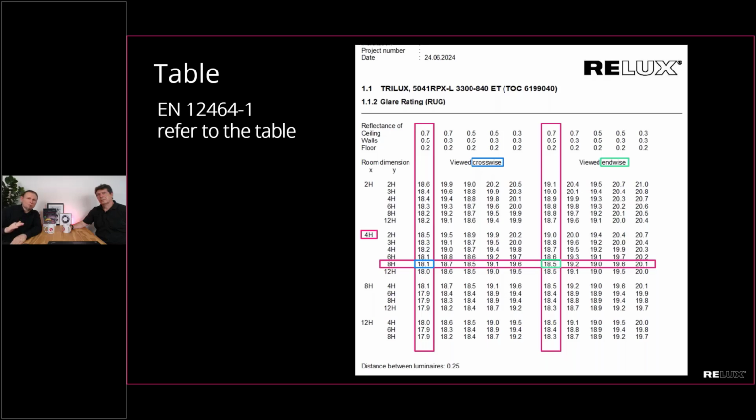But if there is no room involved in the situation, then this is some kind of standard room size which is referred to in a lot of data sheets. So if you find just 1 UGR value for a luminaire, then this potentially means 70, 50, 20 and 4H, 8H for the room orientation. I cannot tell why in particular it's 4H, 8H. Maybe it's in the middle of this. Maybe it's the orientation which is perfectly harmonized. There is harmonization and the golden cut and so on. I don't know. And then we have two values.